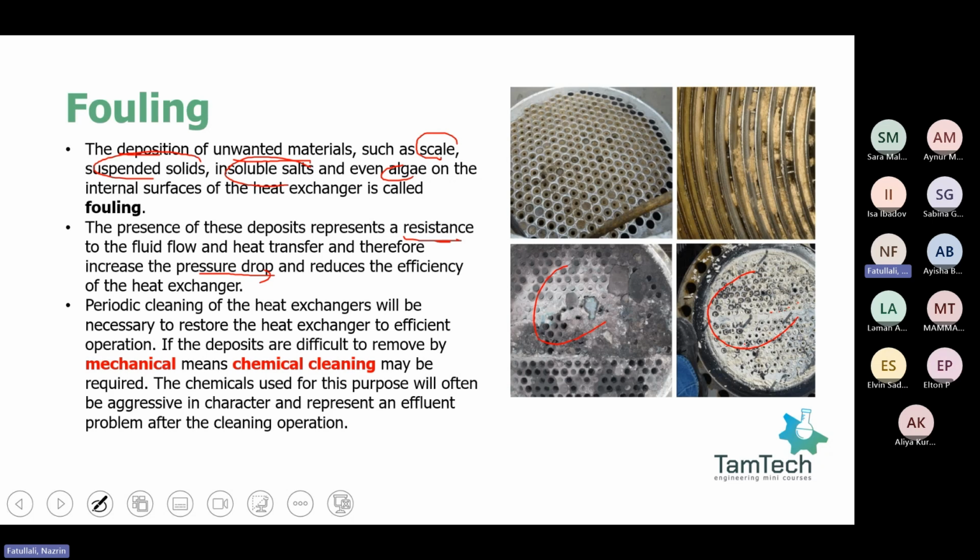If you use, for example, unpurified or unclean crude oil, it will also cause issues because biological fouling can happen. Here it can be algae, it can be biofilm. It can mostly occur in cooling towers because we constantly use water here. That's why algae sometimes cannot be avoided. Also, if you are dealing with hot crude surfaces, coking can also occur. But what is the solution for them?